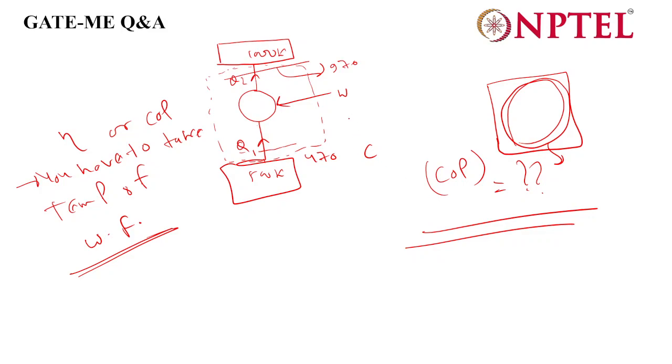Can you kindly repeat this point? Sir, it should be 1030, right? Why? Because heat is flowing from the low temperature side toward the 1000 Kelvin side, so work is being given. So sir, there it should be 1030 instead of 970. Otherwise heat will not be able to flow into that 1000 Kelvin space. I think it should be this only. One minute. Yes, sorry, 970 is not right, because heat goes from higher to lower. So 500 to 470, and 1030 to 1000. Yes sir, now it is correct.